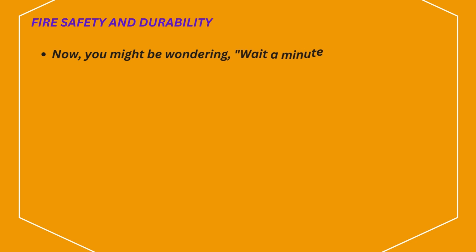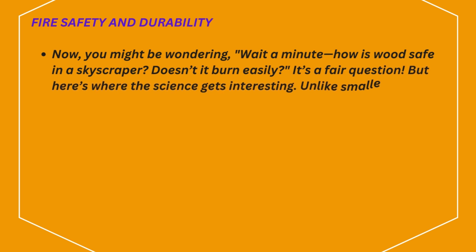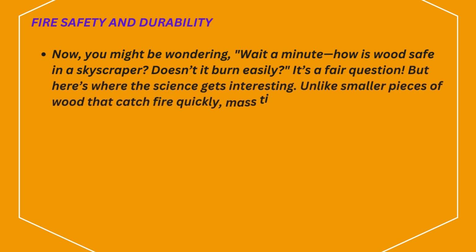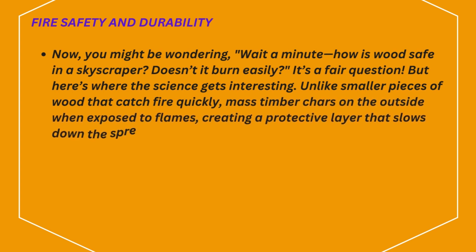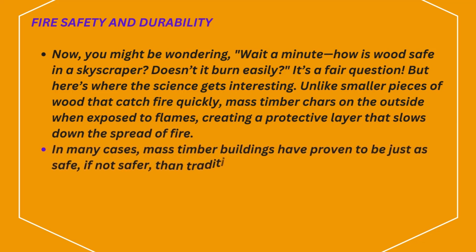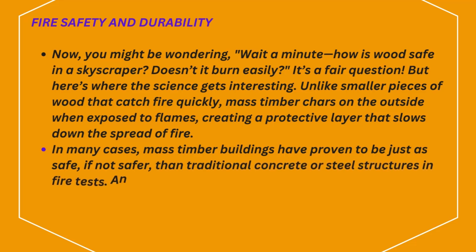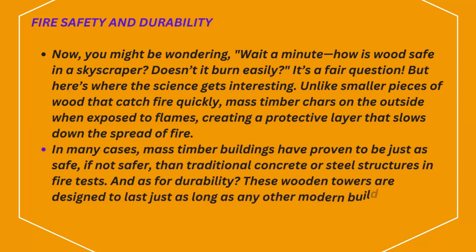Fire safety and durability. Now, you might be wondering, wait a minute, how is wood safe in a skyscraper? Doesn't it burn easily? It's a fair question, but here's where the science gets interesting. Unlike smaller pieces of wood that catch fire quickly, mass timber chars on the outside when exposed to flames, creating a protective layer that slows down the spread of fire. In many cases, mass timber buildings have proven to be just as safe, if not safer, than traditional concrete or steel structures in fire tests. And as for durability, these wooden towers are designed to last just as long as any other modern building, with minimal maintenance required.